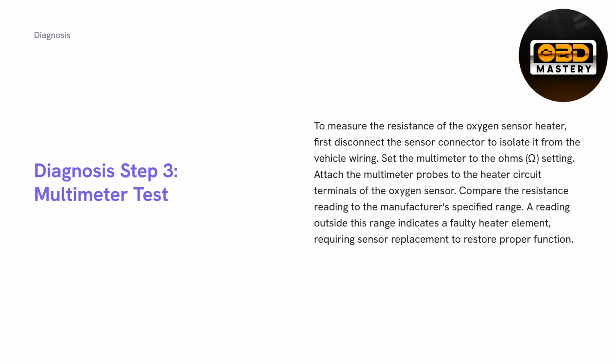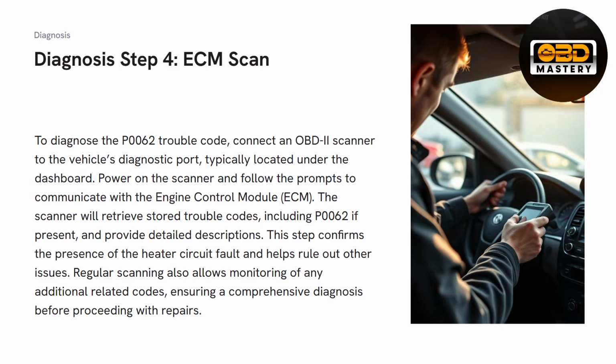Now compare the resistance reading to the manufacturer specified range. A reading outside this range indicates a faulty heater element, sorry about that, requiring sensor replacement to restore proper function. Now, diagnosis step 4 is an ECM scan. However, it isn't really recommended.